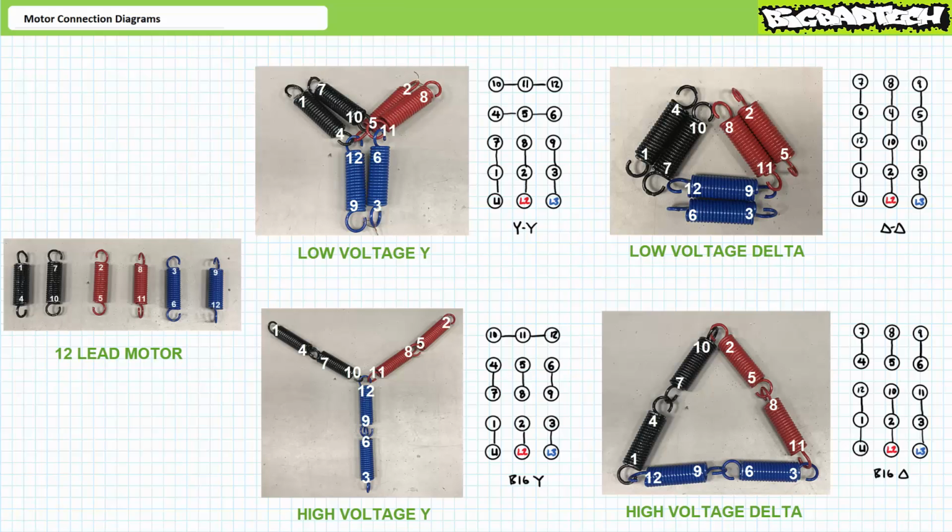I must remind you that winding 1-4 and 3-6 occupy different physical locations around the circular perimeter of the stator, and nearby windings are dependent upon 1-4 and 3-6 of not only doing their job, but doing their job at exactly the right time. Improperly connected 1-4 would peak too early and 3-6 too late. The incorrect electrical connection of these windings would result in a hitch or an outright disruption of the rotating magnetic field. Similar cautions can be made against hooking windings in a reverse fashion since current direction influences magnetic polarity.